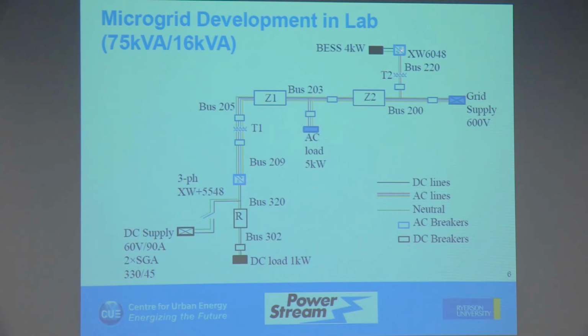If this acts as a generator sometimes and as a load at other times, we have to make sure that it is always within the boundaries of this generator acting as a source. Now this source might be supplying zero power because all the demand is satisfied locally by other generators, but that doesn't preclude it from becoming a slack bus. As long as the power sent out is not negative, the slack bus can still be functional.